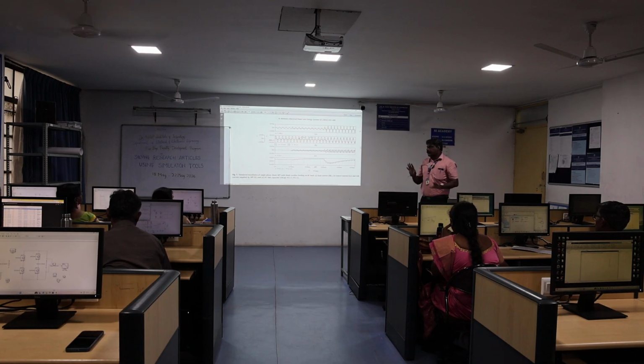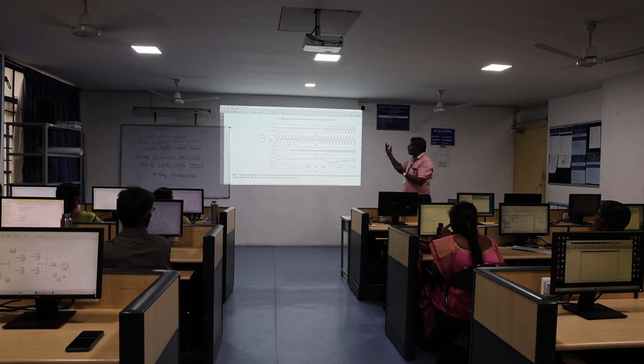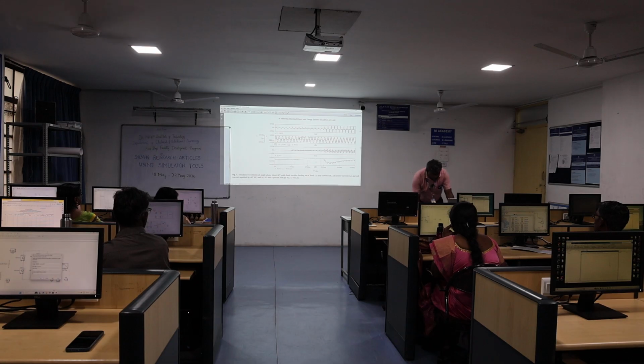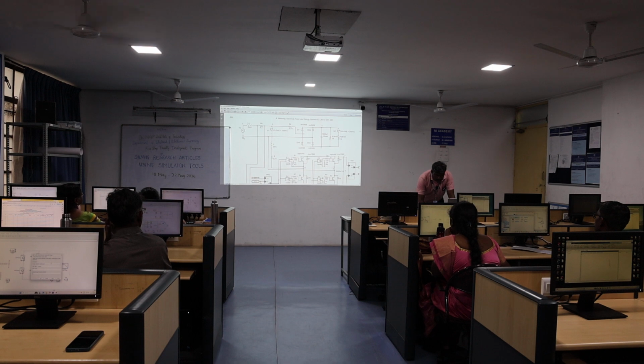So this is for single phase, okay? You can also connect another type of load. You can connect an inductor in series with R load. After the diode rectifier we connected a capacitor as a filter; you can connect an L filter also. So this is for capacitor and resistive load.